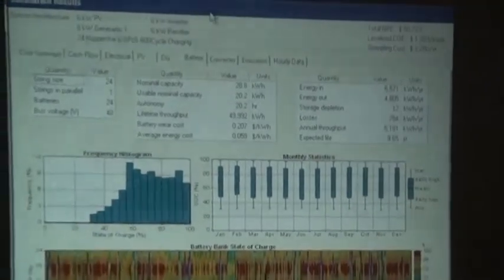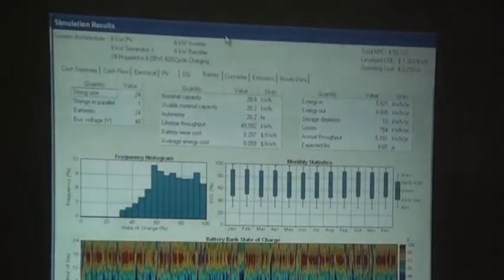So if you have another bunch of batteries, let's say this is a 600 Ah battery here, and you have another 600 Ah battery, it ultimately increases the autonomy of the site from maybe 20 hours to maybe 40 or 42 hours. At the same time, it gives you redundancy, but that also increases your capital expenditure. So you can try to make it 2 strings of 300 Ah or 400 Ah, and see what the outcome looks like. Maybe it can be a more efficient way, but you have to try it.